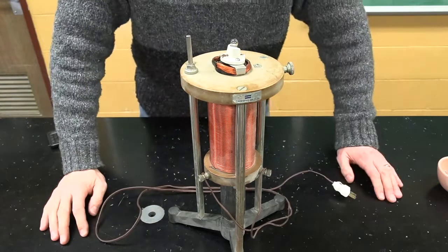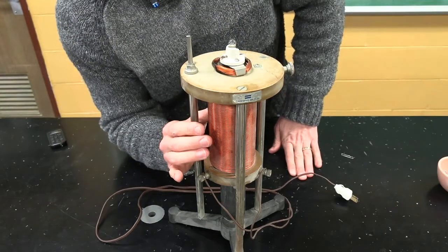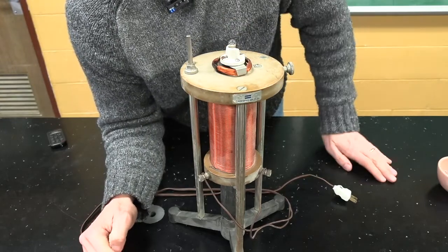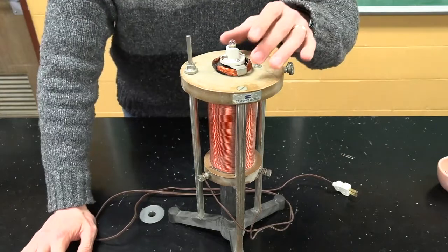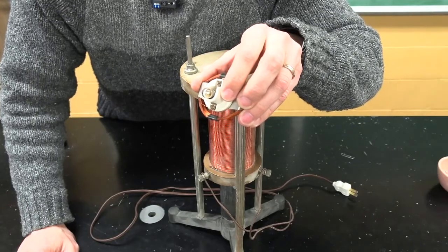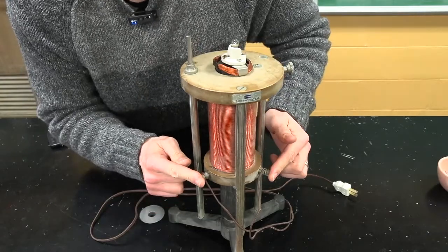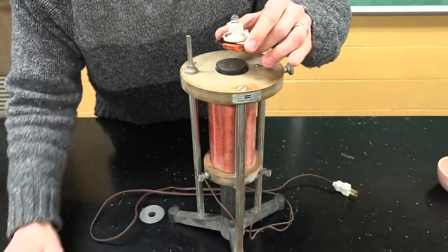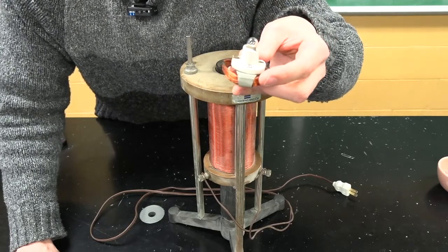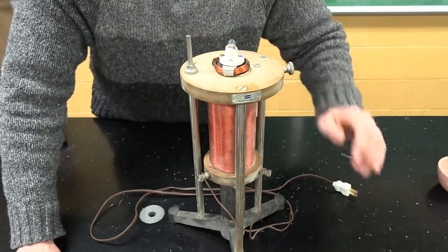This brings me to another important application. What I did is, as I said before, I'm transferring electricity from this coil to this coil without any electrical contact, only through magnetic effects. Furthermore, this little light bulb, if I hooked it straight to the wall outlet, it would burn out. It's too many volts. What I did is I took voltage here that was 120 volts, and because of the magnetic effects, it changed the voltage to something around 3 or 4 volts to safely operate this bulb, which is another very important thing of oscillating or alternating current.